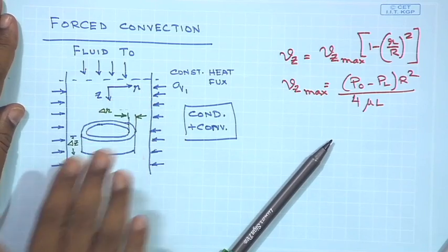and the treatment of this will underscore the utility of having a generalized equation, which, like the Navier-Stokes equation that we have discussed before, will make it possible not to use this shell heat balance for complicated geometries, but have a general equation in which all the terms which are not relevant can be cancelled to obtain the final form of the energy equation, the final form of the heat transfer equation.